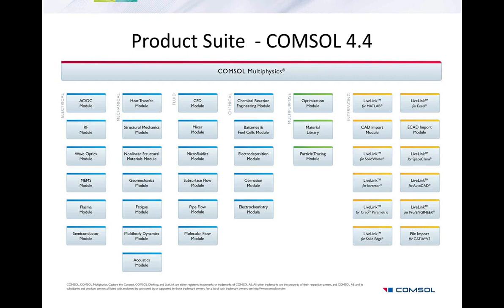Another question: can you explain the difference between the K epsilon, low Reynolds K epsilon, and the K omega, and tell me when I should use each of them? Well, the low Reynolds number K epsilon model resolves the flow all the way to the wall, whereas the standard K epsilon model utilizes wall functions to model the flow in the near wall region.